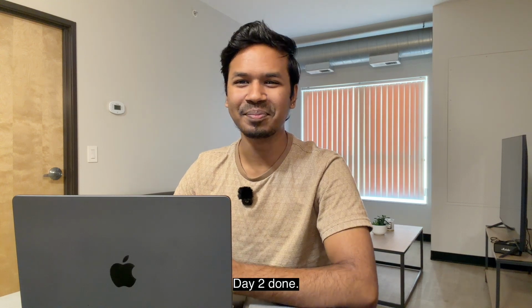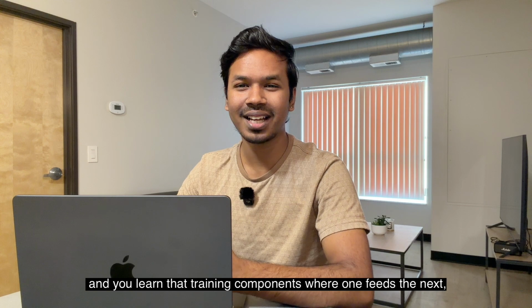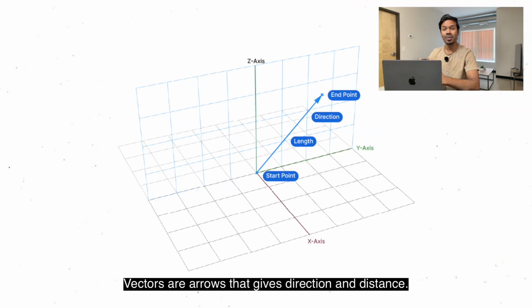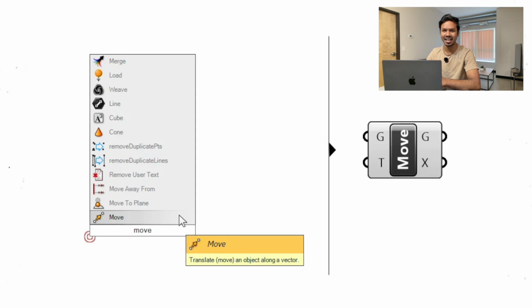Day 2, done. You built a parametric line, you built a parametric circle, and you learned that chaining components, where one feeds the next, is how the complex Grasshopper system works. Tomorrow is day 3, vectors. Vectors are arrows that give direction and distance. You use them to move geometry precisely, and you see the move component for the first time.